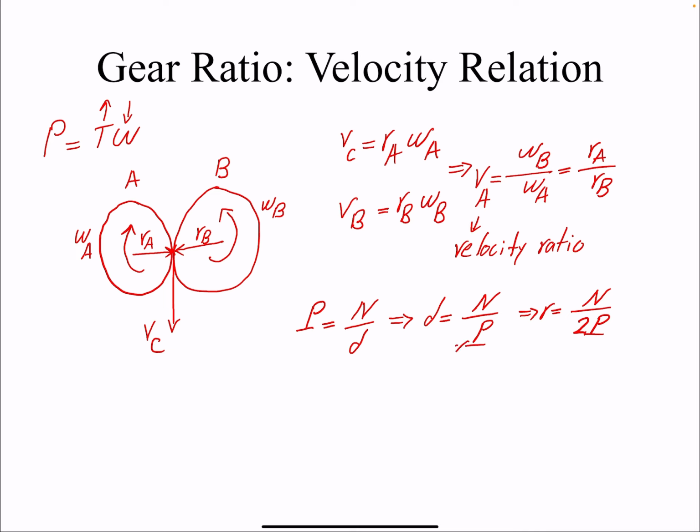The diametral pitch just determines how fine or coarse our tooth is, and it would be the same for gear A and B. For two gears in contact, one of them cannot be finer than the other one. So they need to have the same diametral pitch, or their number of teeth over diameter ratio should be the same.